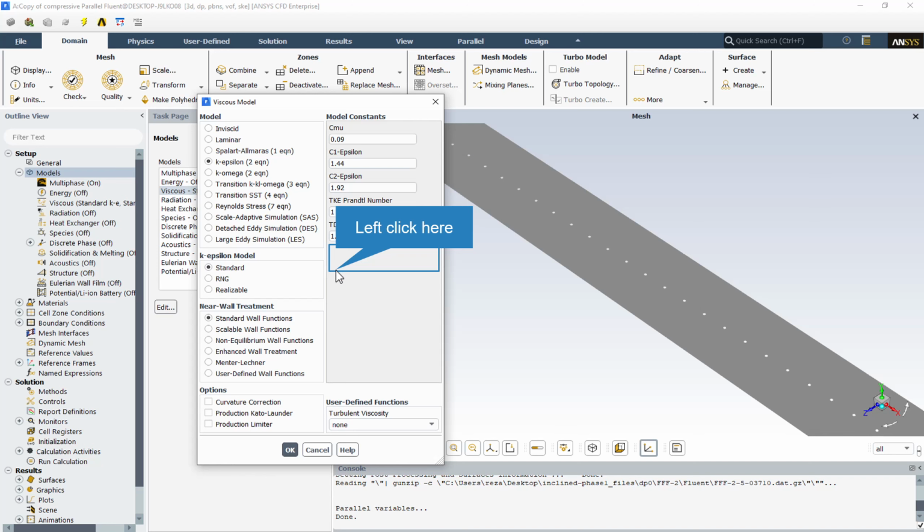In the viscous model, the standard k-epsilon model has been used. That is a two-equation turbulence model that allows the determination of both a turbulent length and time scale by solving two separate transport equations. The standard k-epsilon model in ANSYS Fluent falls within this class of models and has become the workhorse of practical engineering flow calculations since it was proposed.